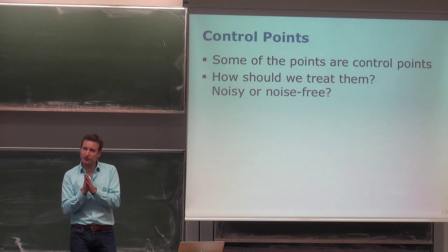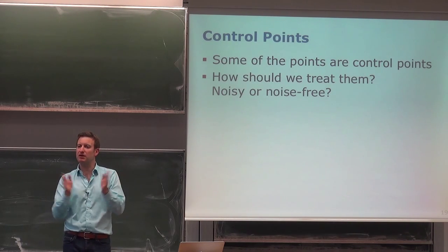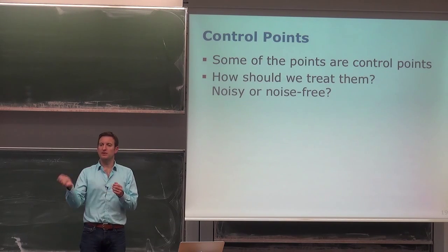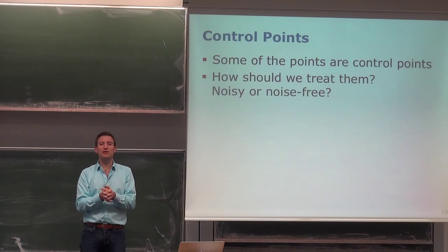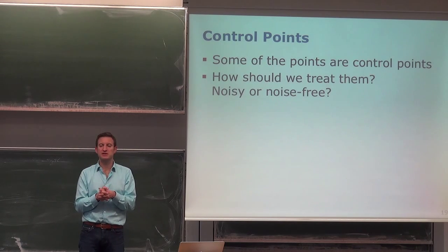This could also allow me to do things like check for gross errors. So maybe there was a gross error or an assignment error between the control point and what I'm measuring, or when measuring the control point, so that there may be outliers in those points, and I may be able to identify them, using the additional information that I have from my camera information.